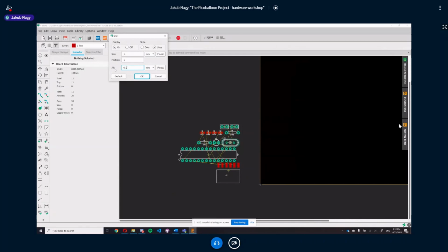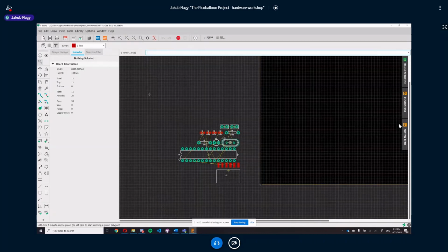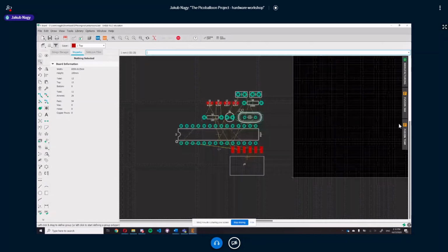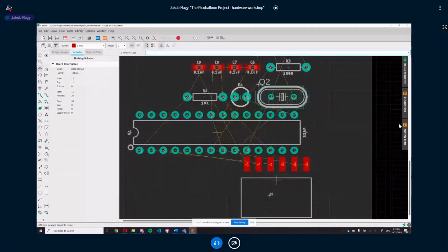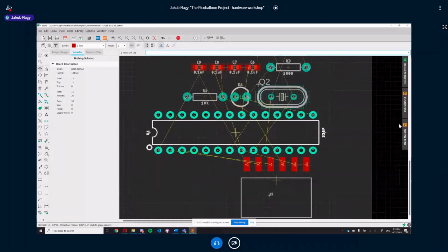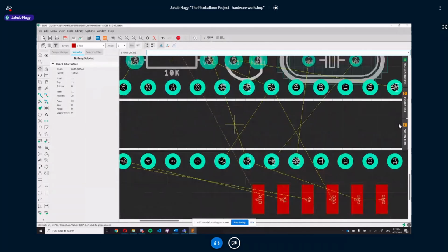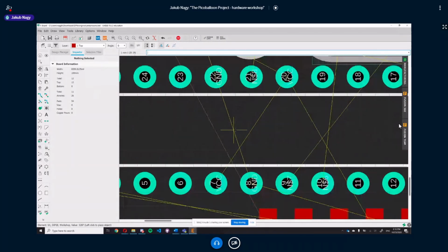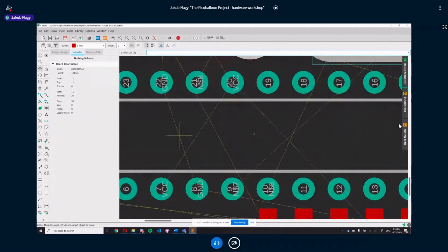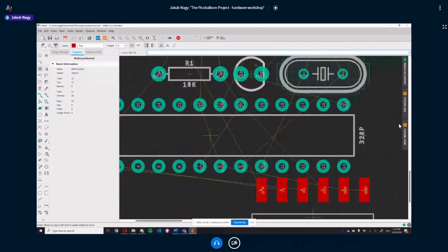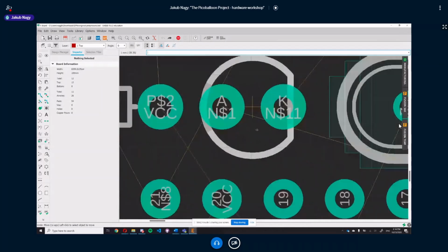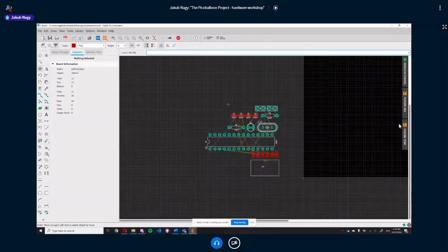And what this means is behind the alt tag. So now I have a millimeter grid, and I can move stuff a millimeter in each direction, but when I press alt, I can move stuff around a tenth of a millimeter, which is nice if I need some additional precision. Now I just return to the original position, and you can also see that the stuff is misaligned because originally it was the inch grid.